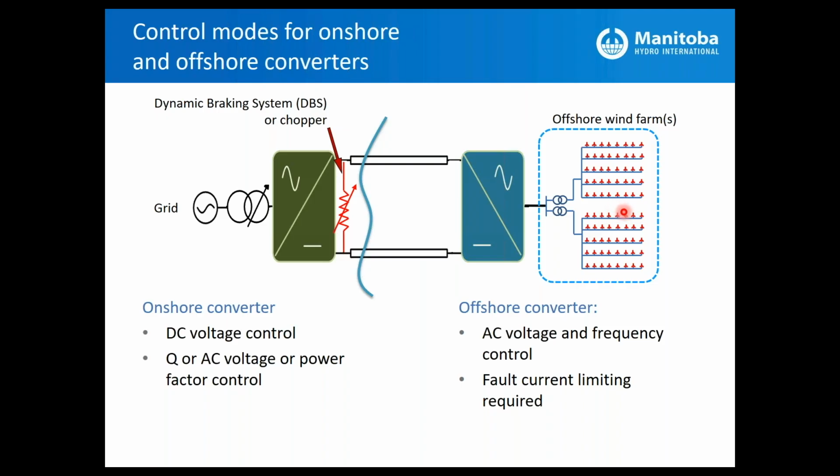They can lock onto it and synchronize to it, and the natural power flow on the offshore network causes the power to go from the AC network into the AC terminals and be transferred to the DC link, giving power transfer from offshore to onshore through the HVDC link. And similar to what we saw for the full converter-based system, in case there is a fault on the AC network, the offshore network will not be affected by that.